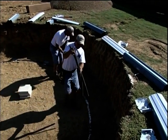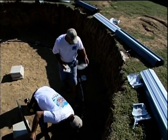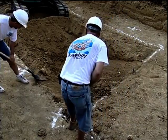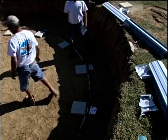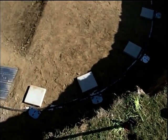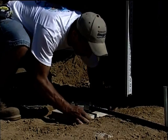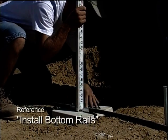Some pools will have transition rails to transition from the circular ends to the straight sides. If the soil in your area is relatively soft, your local codes may require you to use 12 by 12 by 2 inch patio blocks under each of the vertical end caps. If you are going to use patio blocks, they must be level with the pool floor. Please reference Install Bottom Rails.